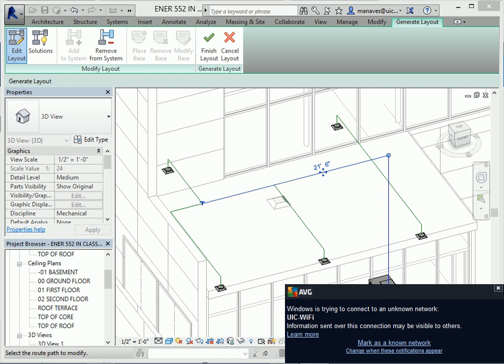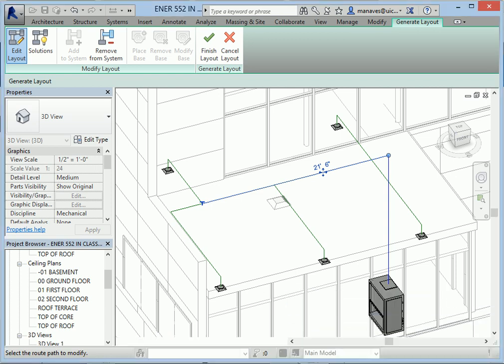So let's look at some other possibilities. We can do this and we'll see what problems we run into. When you ask how do you lay out diffusers, a lot of it depends on how you are going to be able to supply those diffusers, because you might not want them lined up. Especially if you're doing taps, if you're trying to tap into something, you might run into problems. There might not be enough material there. So these are the issues we're going to run into.